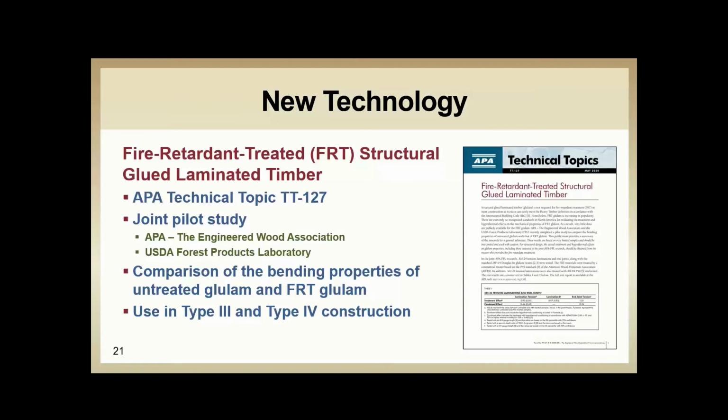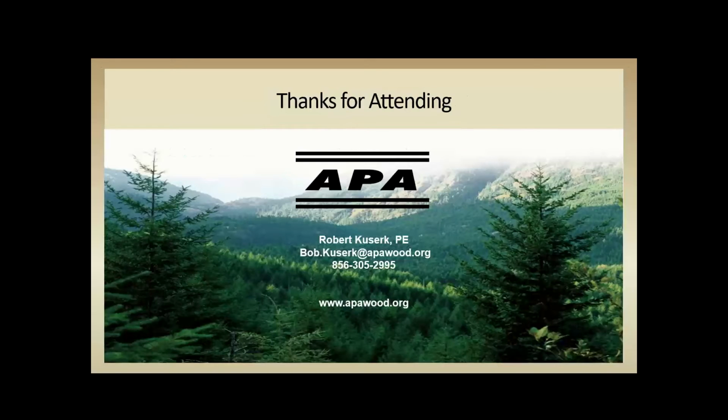For structural design, the actual treatment and hydrothermal effect on the glulam properties will still need to be obtained from the treater who provides the fire retardant treatment for the process. But it's something I want to let people know, that APA is working on getting FRT glulams out into the marketplace as we do see some demand for this product. And with that, that really completes my portion, where we hopefully focused on stock glulam and some of the APA tools that can help at this point.